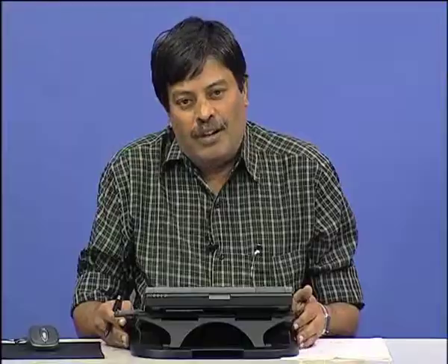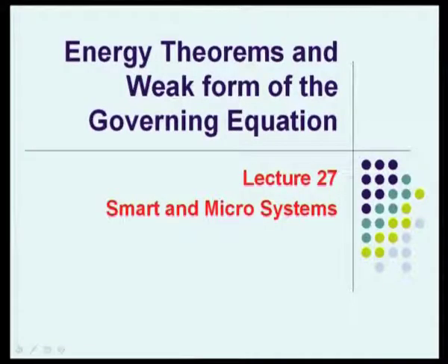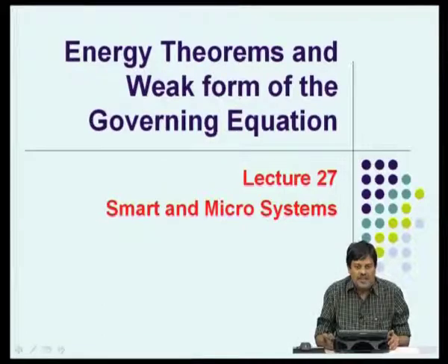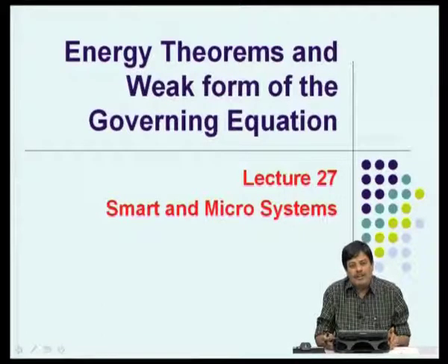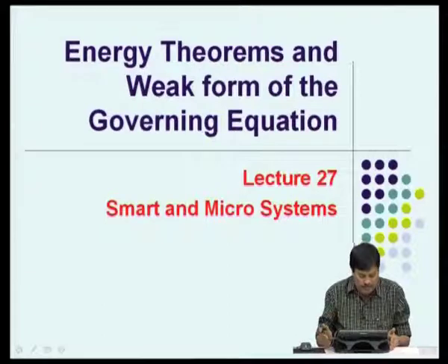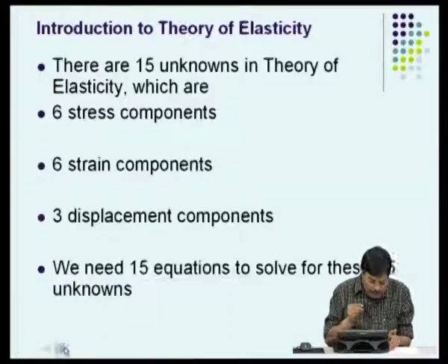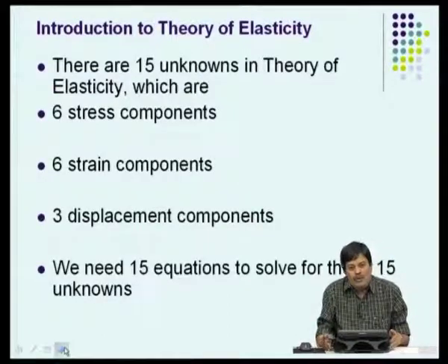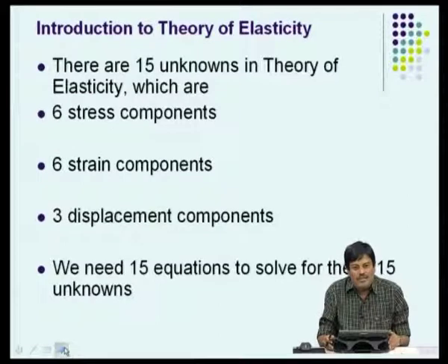So, today we will talk about the theorems that led to the weak form, and also the energy theorems based on which the weak form will be constructed for some structures we normally use in microsystems, such as beam structures. Before we go into the energy theorems, we need to understand basically the theory of elasticity.